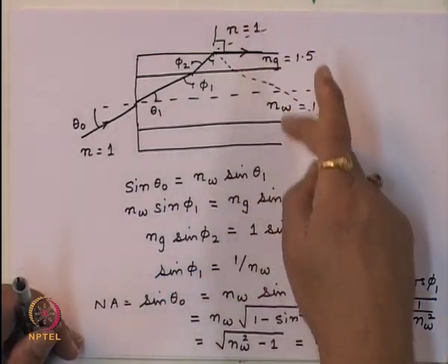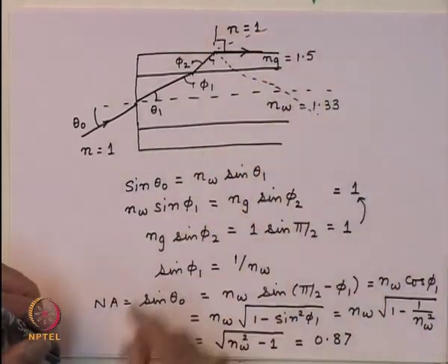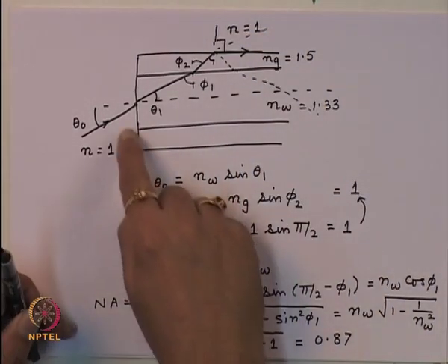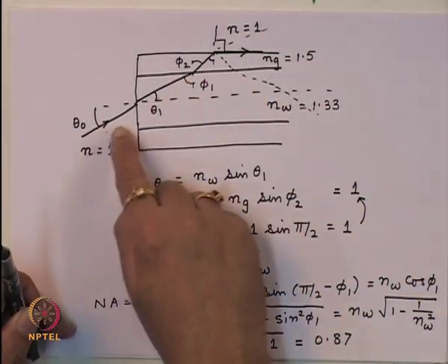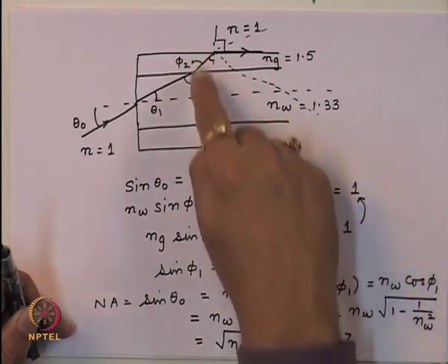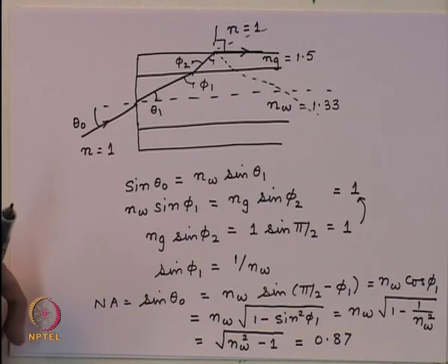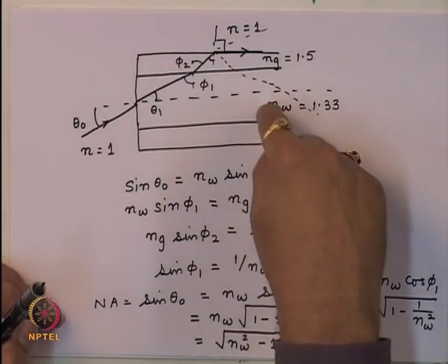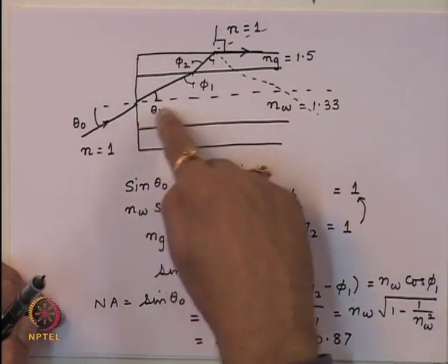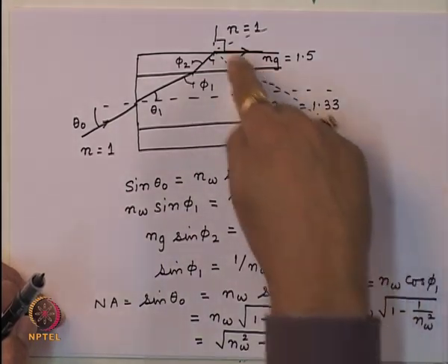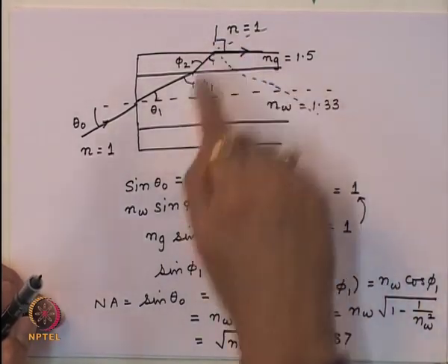But if you have a medium outside, which is air, then the light is not guided inside the core, but the light can be guided at the cladding air boundary. So, even if you have a core refractive index smaller, there is a possibility of guidance of light at this interface, which is the cladding air interface.